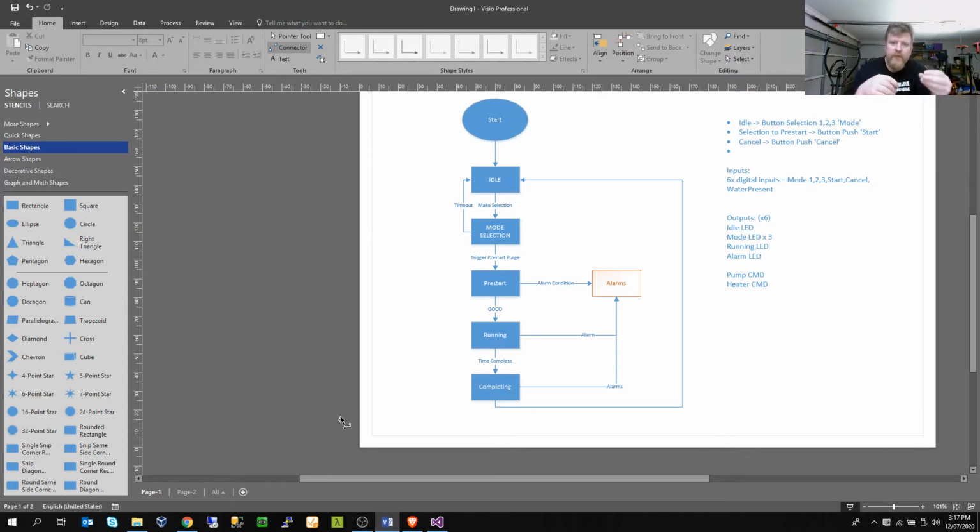One of the things that's specific to this kind of process is that it doesn't have an upstream and a downstream process. So it's not a production line. It's not a continuous production. We don't have a machine that loads the dishwasher. We don't have a machine that unloads the dishwasher that it has to interact with. So in this case, a finite state machine is an excellent choice.